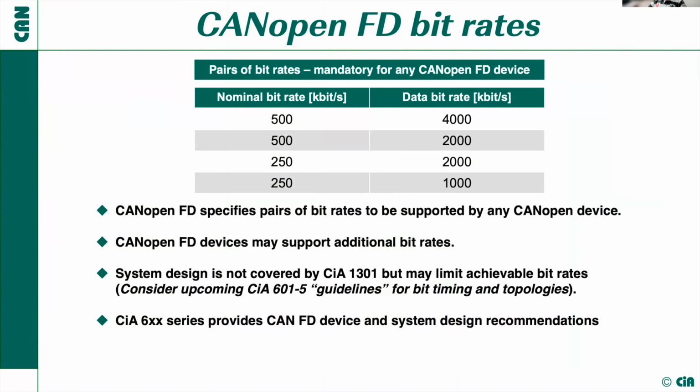And now as the physical layer design and the data link layer design gets a little bit more tricky in CAN-FD compared to CAN Classic, we thought, okay, it is wise to provide some stronger recommendations up to specifications to allow interoperability of CiA OpenFD based devices out of the box.